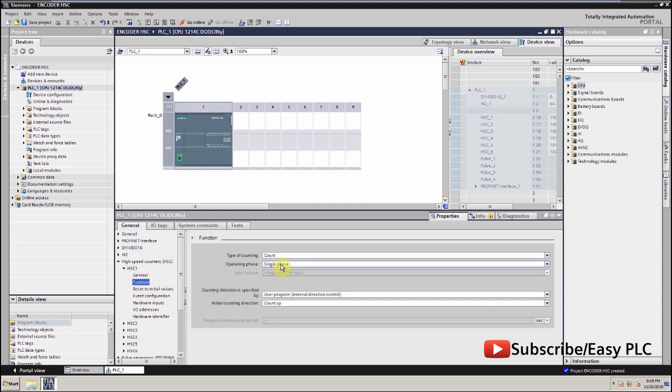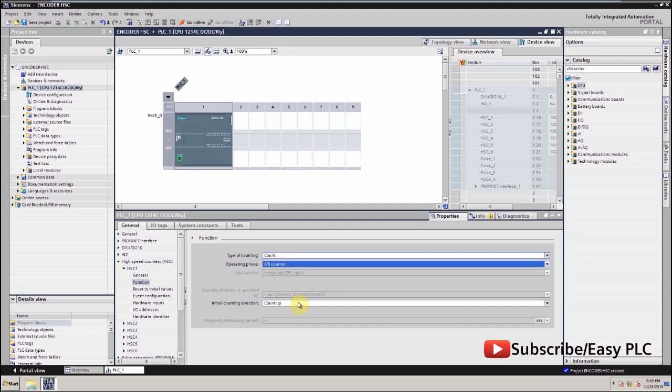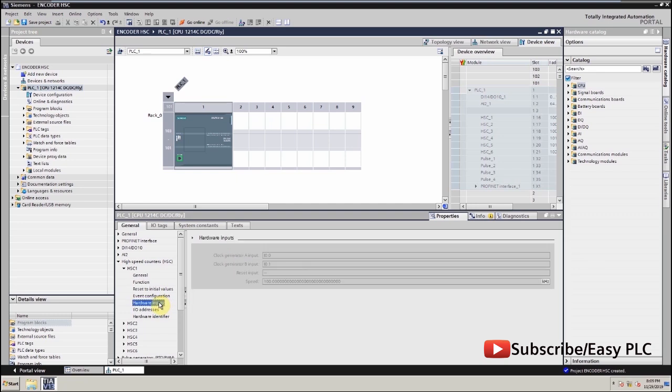For the function menu, there are different options regarding high-speed counter. You can select as per your requirement. I will select AB counter mode from operating phase. From hardware inputs, we can see the PLC inputs where we have to connect encoder outputs. We have connected encoder outputs to I0.0 and I0.1.